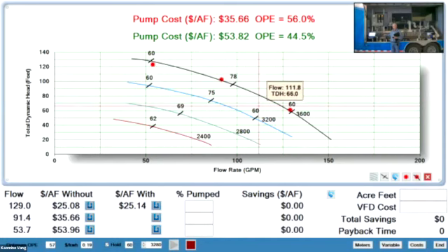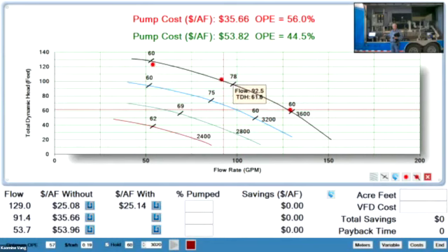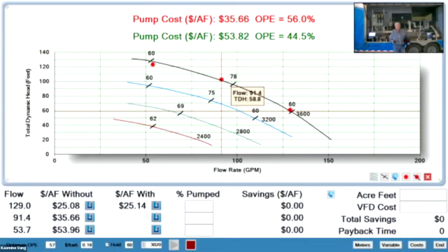Hear the pump slowing down? Now we were pulling about 4.6 kilowatts. Now we're slowing down, and it'll show the RPMs down there, how much they're slowing down. And I'm trying to match up the flow rate here. It's hard to hit it perfect, but oh boy, I might have nailed it. No. It's hard to hit it perfect, but I'm pretty close. I'm going to go with that. A little bit more. There we go. There we are. Let's mark that spot. All right, I hit it perfectly.